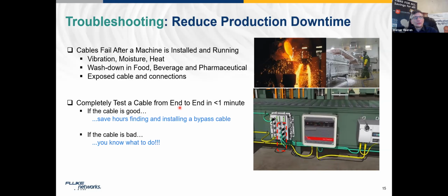That's why you should test your cable from end to end. A little bit different than enterprise environment, where you remember permanent link, that's what stays in place, but you still have your patch cords and your equipment that comes. So in industrial environment, it's more important to test really from end to end.